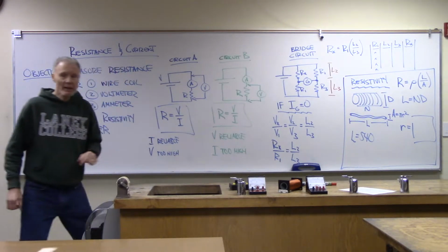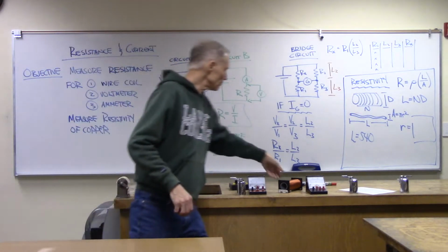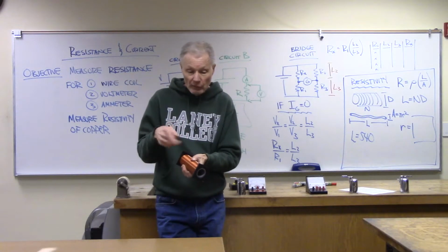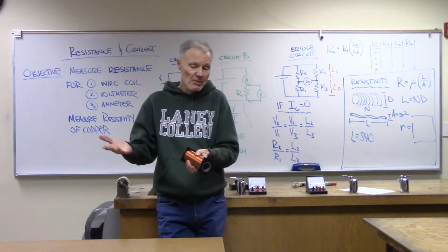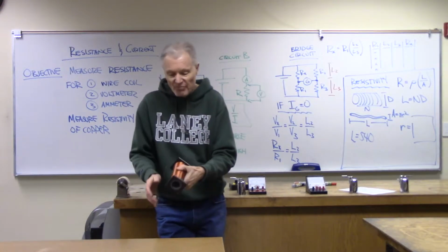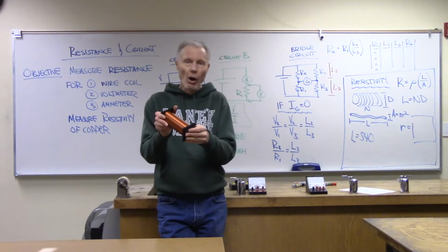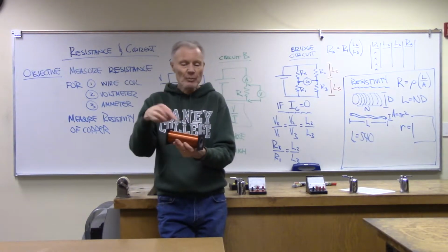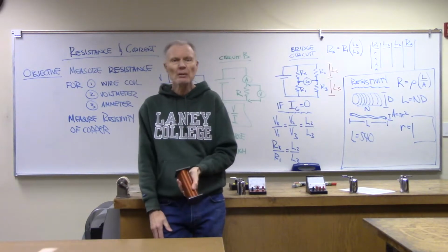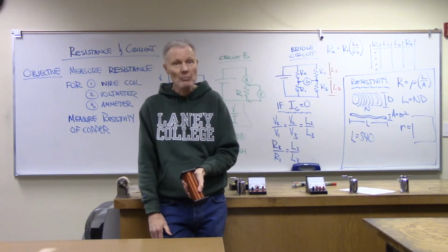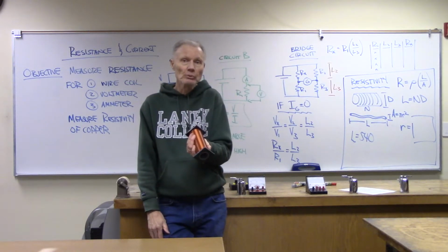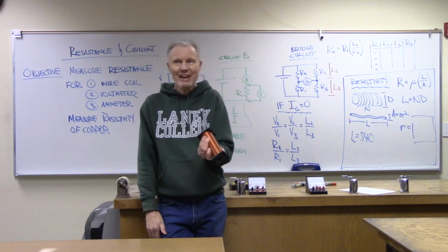So I've got those right here on this front table. This is just a bunch of wire. So it's a coil of wire, so it's really long. I think it's more than 1 kilometer or something. That seems kind of remarkable, but it's a really, really long piece of wire, and it's been wrapped over and over and over and over. And so we want to find out, how much resistance is in a really long piece of wire. And it turns out not much. It's only like 1 or 2 ohms of resistance, and that's kind of what you would expect.